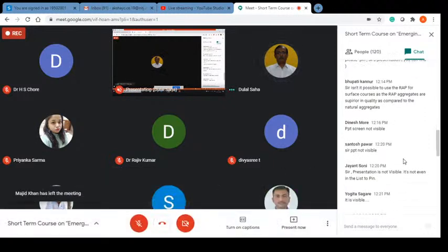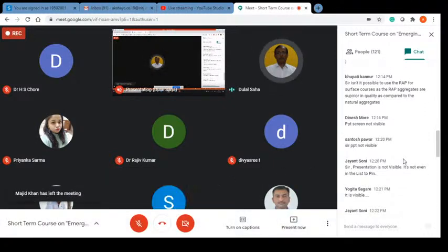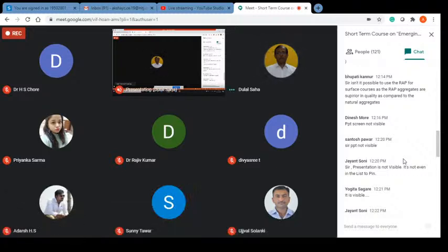So WMM material utilized for base material as per MORTH has been taken as reference material. And then I have done testing on two basic alternative materials. One is RAP and another one is RAP plus WMM 50/50. So for example, if I take my base material, I can compare it with that material. Here I have considered WMM material as per MORTH specification and I have compared the load carrying capacity accordingly. I think this is my response to this.